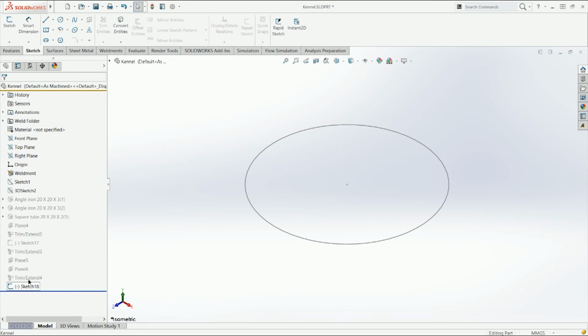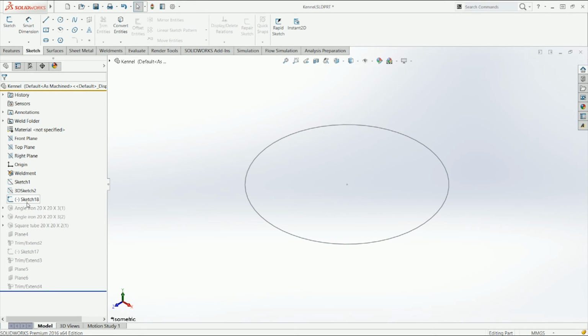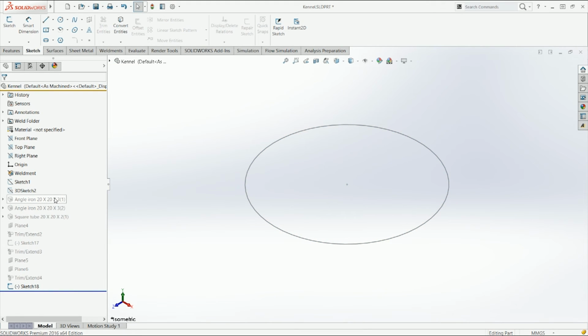If you want to sketch something first and then edit the features depending on that sketch, you can do it if you just drag the sketch up here. But if you don't do that, you would have to go down here again. So I just suppress and create a new sketch, and that's what is showing me right now. It's doing this sketch after all the features.